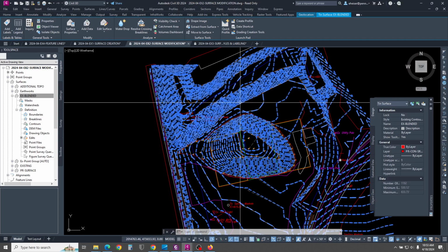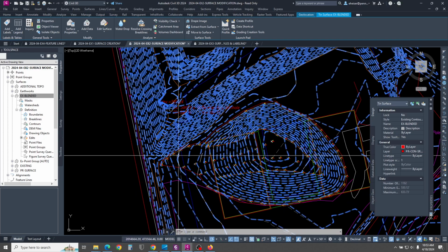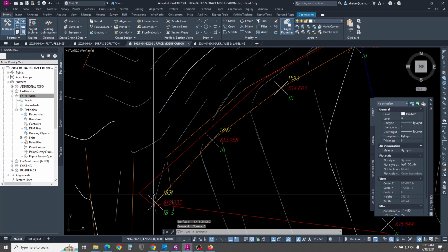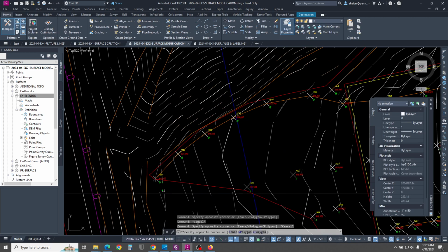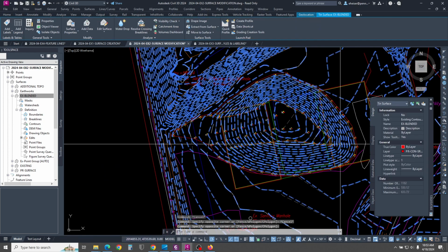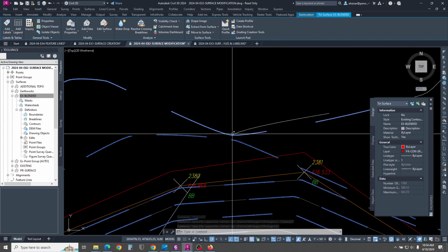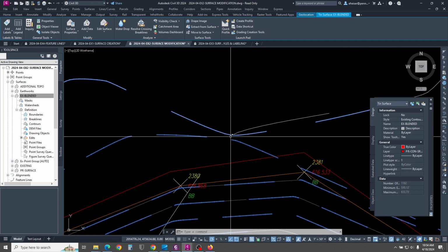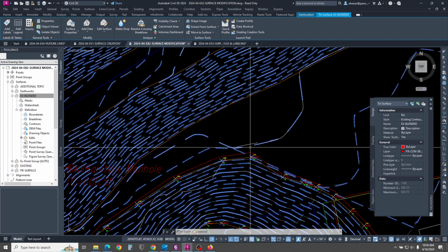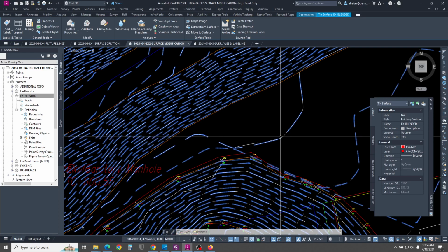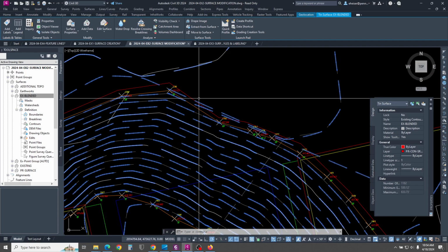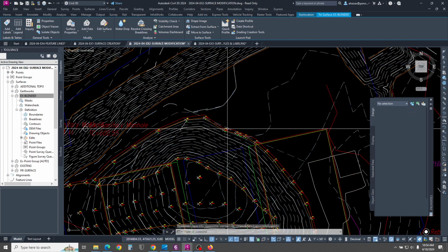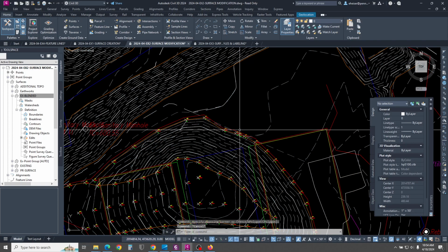What you need to sometimes be careful of when you're blending surfaces is if there's a jump, like between the shots here and the shots that made up this break line, you could get some weird stuff with your contours. You kind of need to just run along the boundary of your surface to check. So for example, this right here, probably not great. They're a little too close together. That would need some cleanup, which you could talk to Survey or a design manager, senior designer who's done this a bunch, and they could probably narrow down pretty quick what needs to change to make that more realistic for what it's supposed to be. Same thing here. But for the sake of what we're doing, we're going to stop at that.